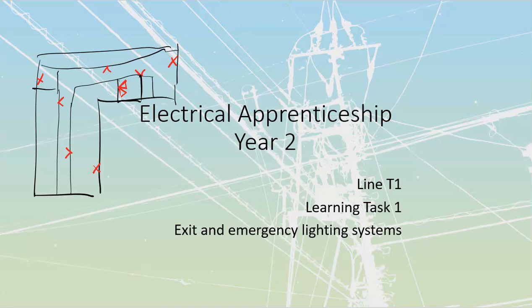All of them are going to have the same sort of things inside of them. First of all, they are going to be battery-powered. We're going to have exit lights that are on all the time, but when the power fails, the exit lights need to be taken over by battery. The emergency lighting is going to be off most of the time, but it's going to come on whenever the regular lighting in an area fails. So if this were my regular lighting inside of these hallways, I'm going to monitor that with this circuit over here that is my emergency lighting, and if for whatever reason the power to that area were to shut off, not the light switch, but the power to it.